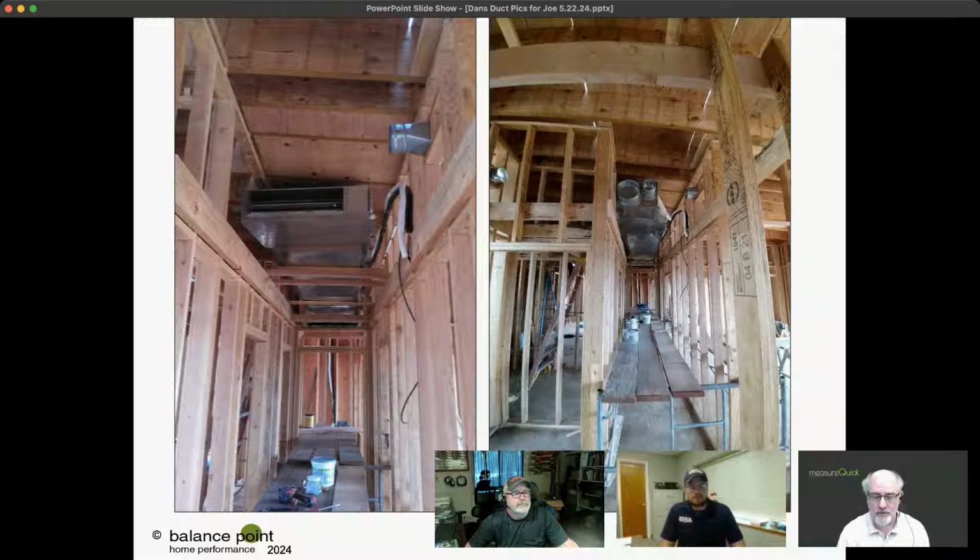I'm sure you still go to some homes and find out that, wow, this is in an attic, and maybe this is not the best place to be putting all of my hot air in a super cold attic. Yeah. So we got two options usually, basement or attic. Honestly, most of the time I prefer attic, even though we're dealing with the hot temperature. Most customers don't care what you do. When I'm in a basement, most of our basements are barely 8 foot tall. Sometimes you get lucky, you get a 9 foot tall ceiling, that you have the room and it's not going to kill the headroom in the house or in that part of the basement. But most of the time we're dealing with 8 foot or under.